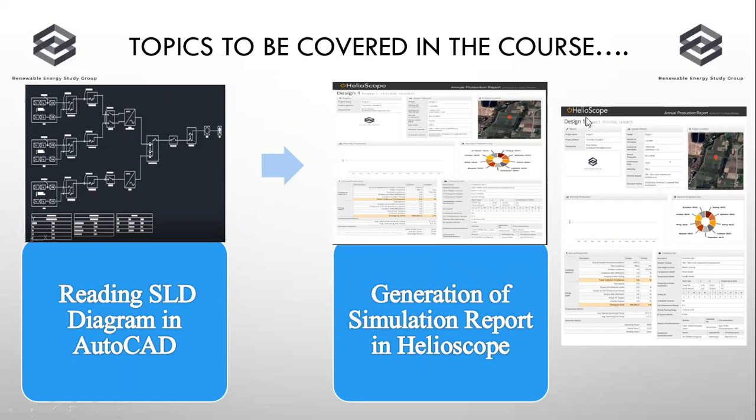And the next thing we're going to see is how to generate the simulation report in the Helioscope software. After entering the simulation parameters, we're going to download this report in PDF format, which consists of information about the site, what different kinds of losses occur in the solar power plant, and according to the energy yield estimation and the further design parameters, we can easily download it from the Helioscope software.